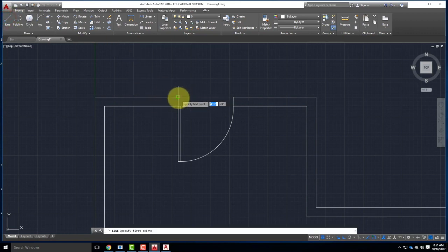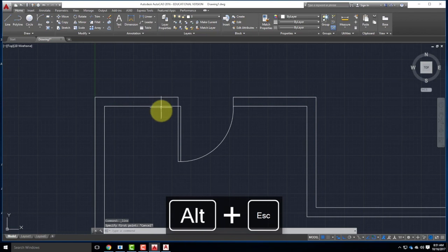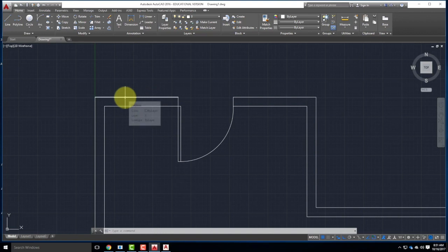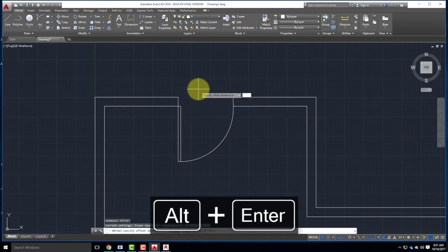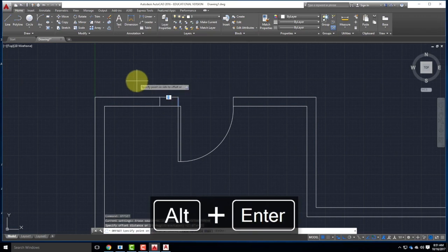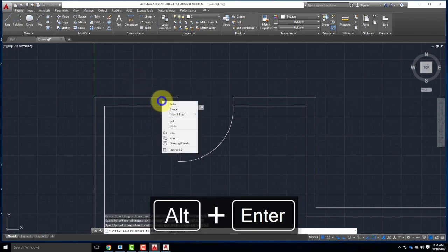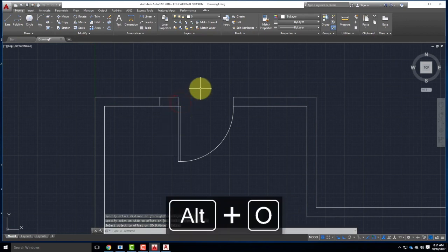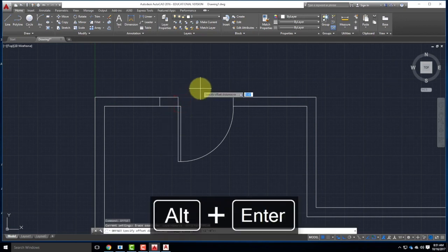So there's a door. Now I need to go ahead and create the window that goes through this. All right. So what I need is I need to go ahead and create a window, and I have some dimensions relative to where the door is. So I have a foot that's over here, and then I have 2 feet for the window. So why don't I take this line, and I'll use the offset command again. My distance this time is only 1 foot, so I'll type in 1 foot followed by enter, and I'll offset that first window. Then I'll repeat the offset command. Offset. This time it's 2 feet because that's the width of my window. So I'll do 2 feet, and there it is. I'll hit enter to finish.